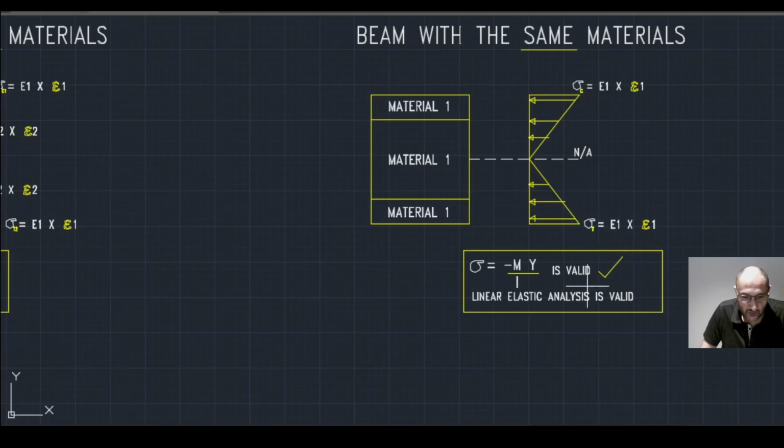Now, provided that we make sure that the shear stress between the materials due to the varying bending moments along the beam is less than the allowable shear stress of the fixings. Whether you are using glue, nails, bolts, or screws, we need to check the capacity of these fixings to keep a unified element. But if you want to bond two different materials with two different modulus of elasticity, then we may need to adopt a composite beam analysis using the transformed area method.